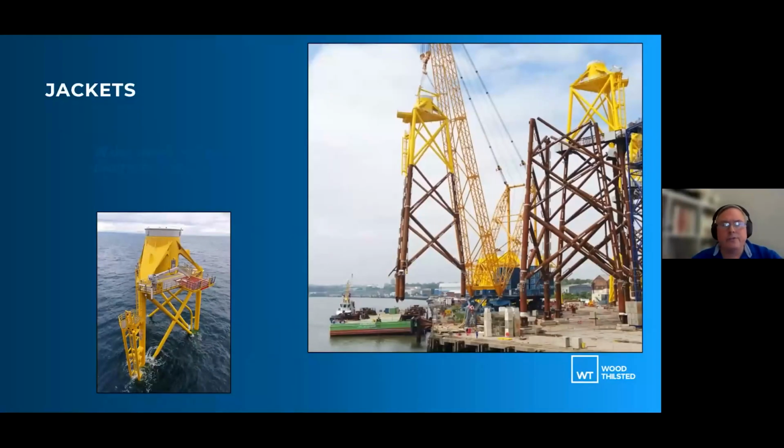So jackets, it gives you an idea of what the structure looks like. Instead of a single tube penetrating the seafloor, it's multiple tubes penetrating the seafloor. And there are certainly advantages to that because you distribute the load to multiple connection points, soil steel interaction points, if you will. And that is particularly helpful in areas where you've got seismic concerns. So in the APAC region, where you've got earthquakes, and off of California, that sort of thing. Jacket structures are being commonly used in APAC as we speak, as that business takes off.